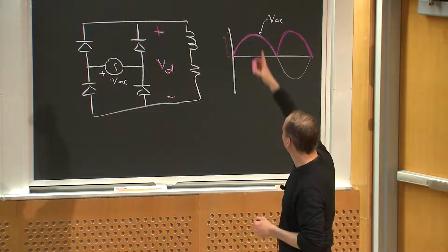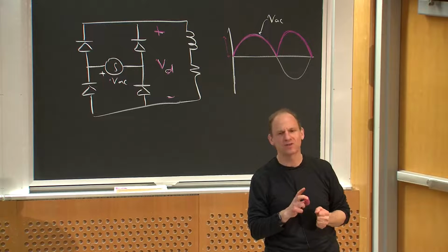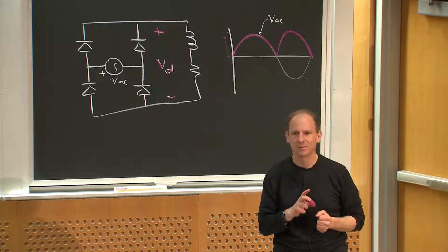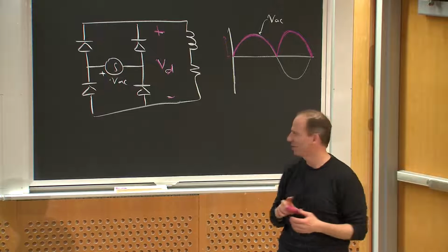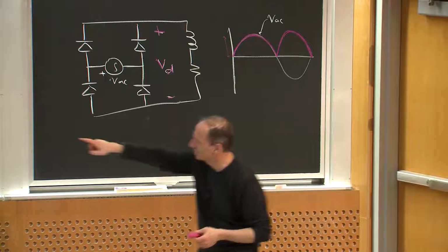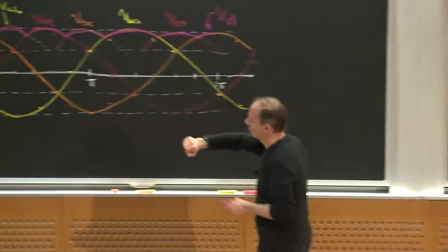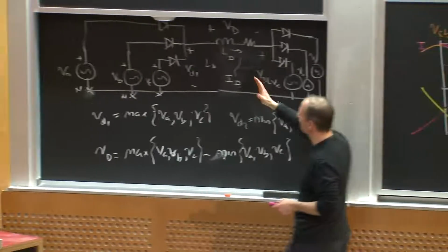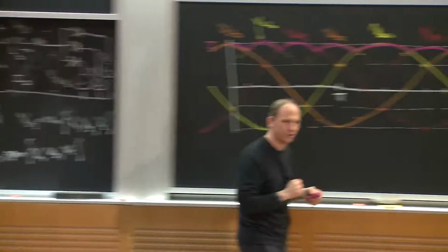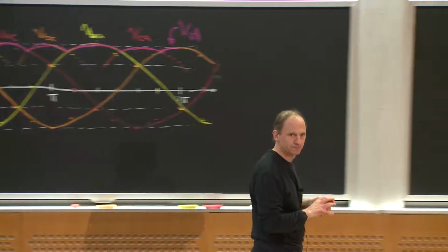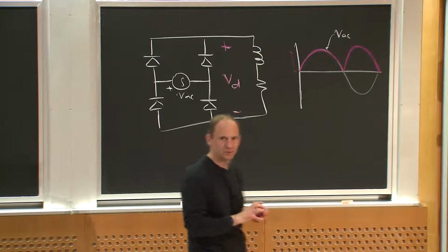And this is probably the simplest version of a three-phase rectifier that you'd actually use. People tend not to use half-wave rectifiers because they inject DC back, and likewise, they tend not to use the simple 3-diode version. So this is kind of the simplest rectifier you'd use for three-phase. Other questions?